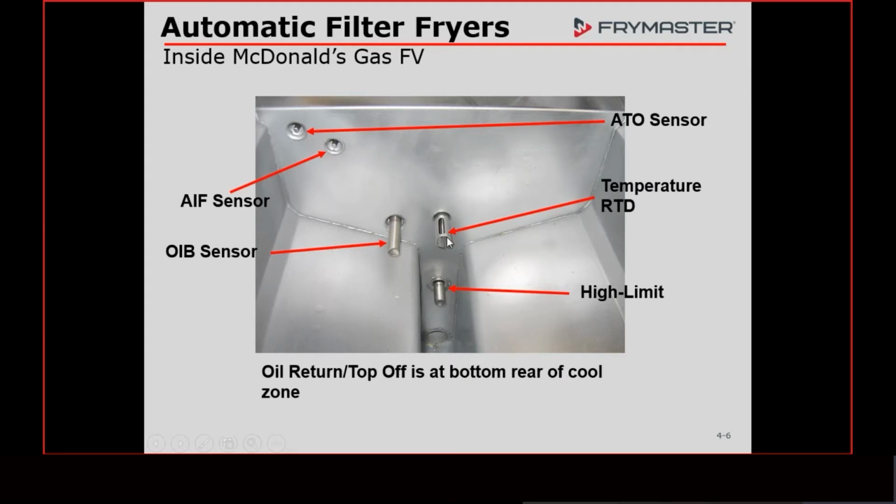On the controllers, any controller that we've ever made, our computers, if we press the temperature button, it's going to tell you the actual temperature of the oil. If we press and hold the temperature button on the controller with the controller off, on a Filter Quick, it's going to give us the temperature of the ATO and the AIF.